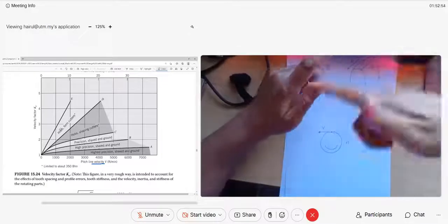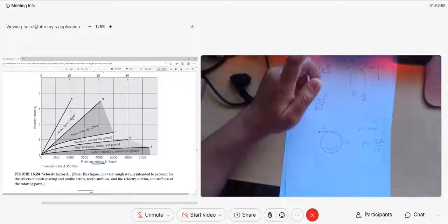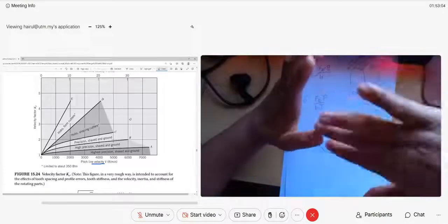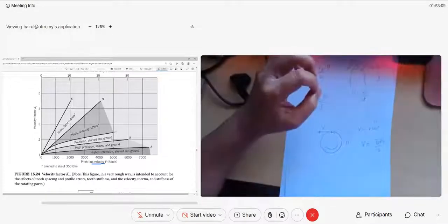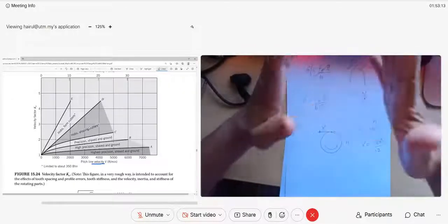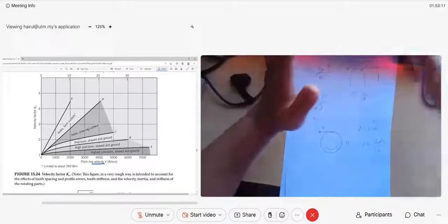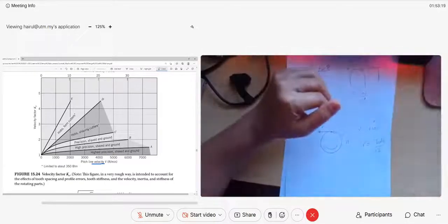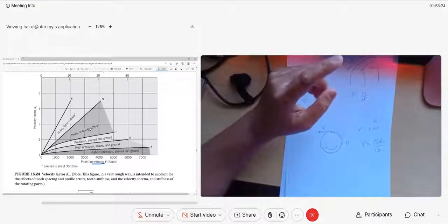I showed you the video, that is hobbing. Form cutters means they form the shape. Form cutters are a little less quality than shaping cutters. They just form as long as they get the shape. Shaping cutters means they are more shaped and more accurate. Cutters are the ones that cut your blank cylinder to make a gear. Typically I think gears are more often hobbed with shaping cutters.